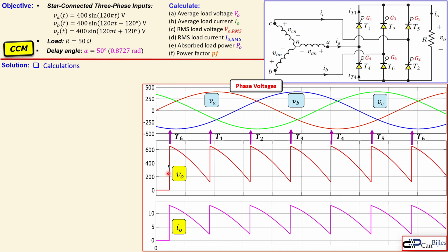You see actually here, so delay angles will make sure that these thyristors will be activated. That creates actually this jump up and then getting back and jump up and getting back. So each time the thyristor will be activated, you see actually here the rapid changes in the currents and voltages. And these are again the line-to-line voltages. You see that in this case, clearly it is not a triangle, actually it is sort of a shape of this voltage part. So also for this VAB, where we use the actual value later for this part, and VAC, etc. for the other parts.